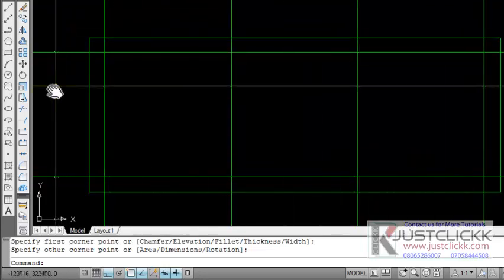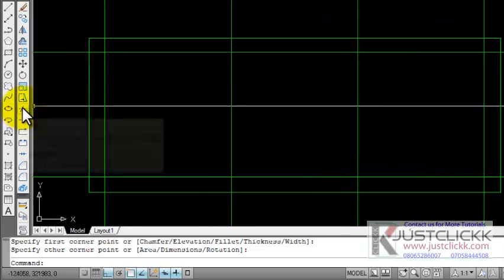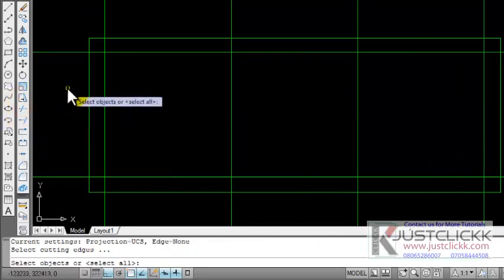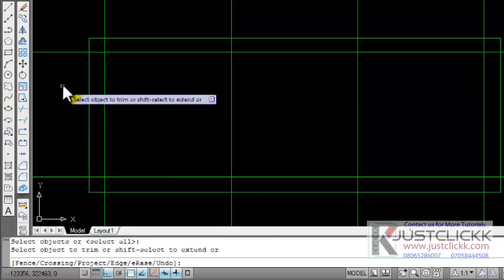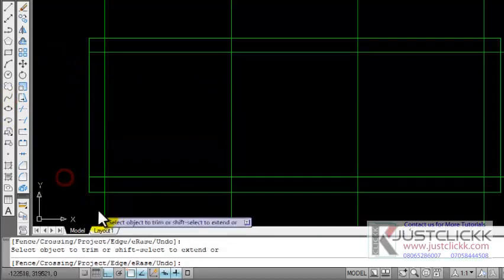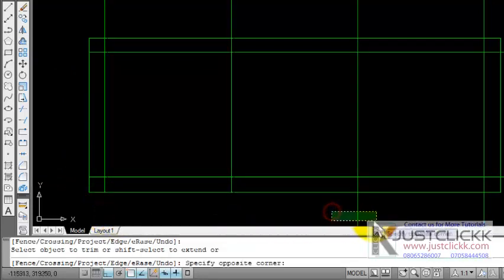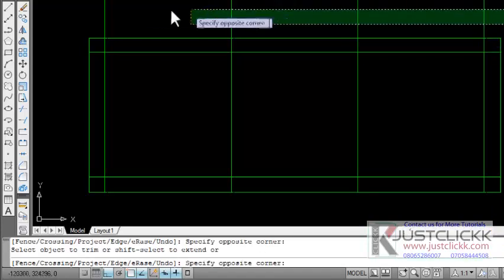So we are now going to use the trim tool by clicking on the trim tool and then pressing the enter key to activate it, and then we'll begin to click on those infinite lines, the excess. Just click them. You can click and then move your cursor that way to select those lines on that axis to trim all of them. So it's something that I call group trim.